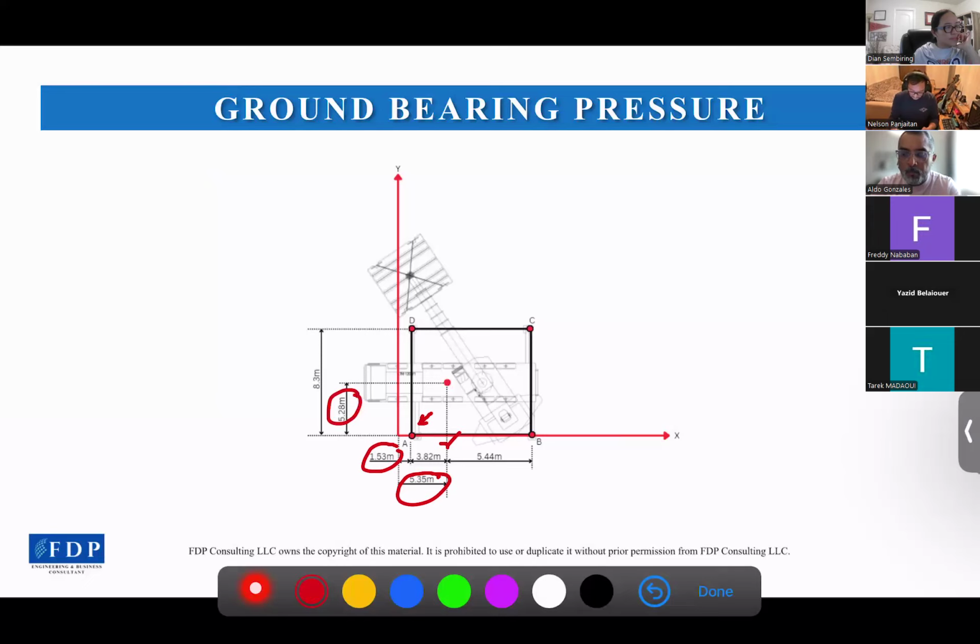So that's our crane COG during the lifting operation. Just for information, the boom slewing angle shown in this picture is indicative only. You might see that the COG here is not in line with the boom.